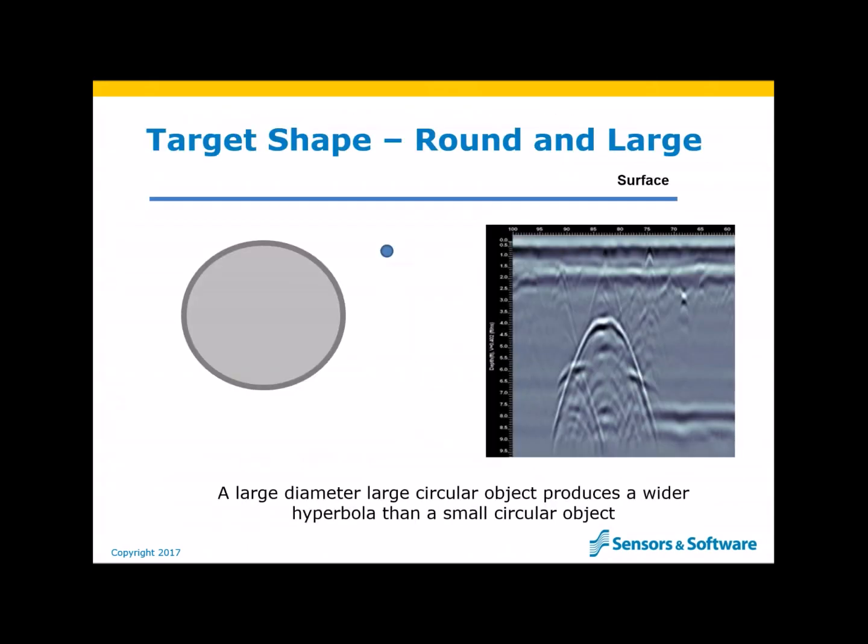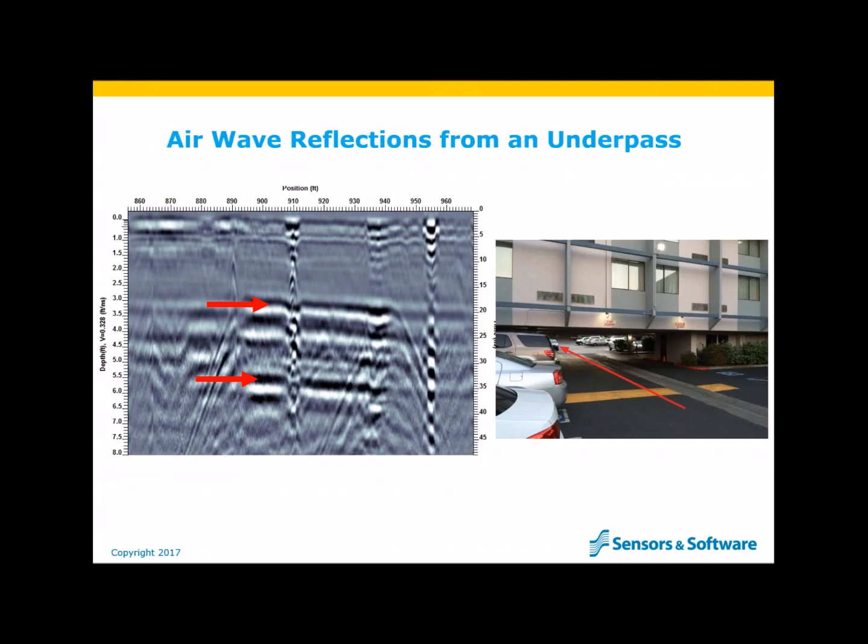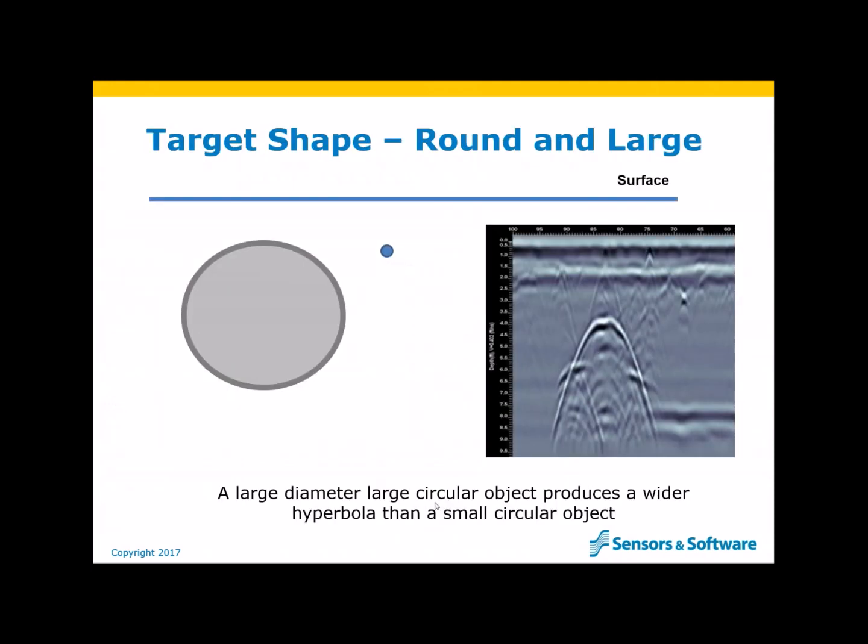And that's when the problems start. So if you see GPR signals fading out and then suddenly there's a stronger reflection, be suspicious of that reflection. I am not saying to automatically interpret it as an airwave, but use what you've learned here to determine whether it is above ground or a below ground object.